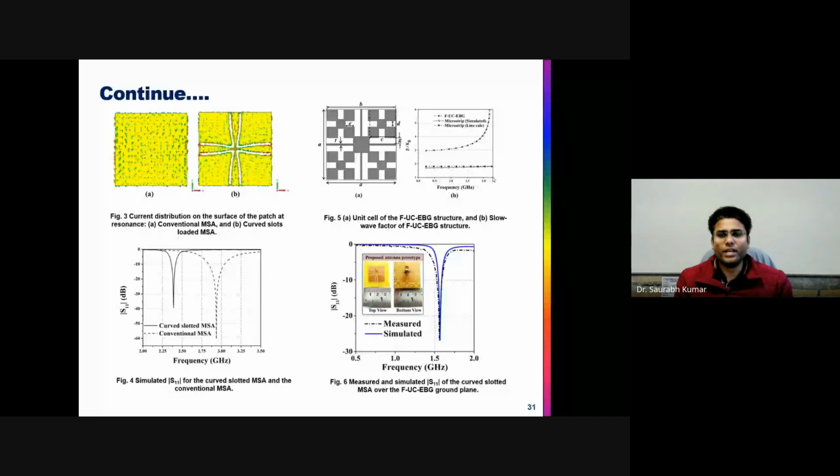What is the meaning of band gap? It means the prohibition of the electromagnetic energy is there. So how is the prohibition achieved? It is not like someone is going in this way and you have just a stop. You have to slowly stop your electromagnetic wave. Your electromagnetic wave is, let's say, propagating with some velocity. Slowly the velocity will be downshifted, or the slow wave factor will increase, so that the velocity of the wave is prohibited and there will not be a propagation within this particular band of frequency.